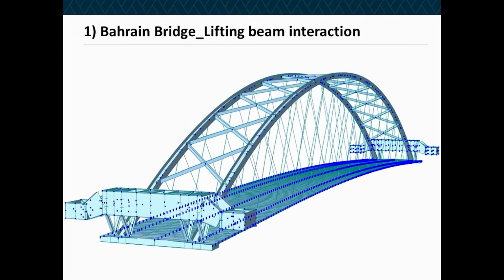Later on, we needed to move this bridge into position. Now there's a few photos after this and a very, very short video that explain that process. But this lifting girder at the end was also modeled in MIDAS. It's a frame model with rigid links to simulate the correct location of the connection of the various different elements. And it's stressed down to the deck. So we actually use this to lift the deck off the supports again, and then we support it on either side. Now I'm guessing that this will be a laser, so we'll try the laser.